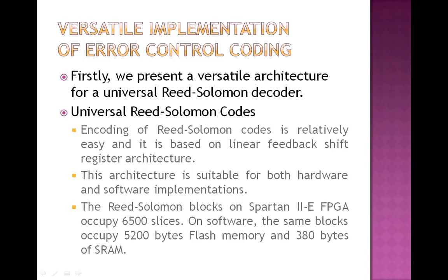First we present a versatile architecture for a universal Reed-Solomon decoder. The universal Reed-Solomon decoder encoding is relatively easy, and it is based on a linear feedback shift register architecture. This architecture is suitable for both hardware and software implementation.